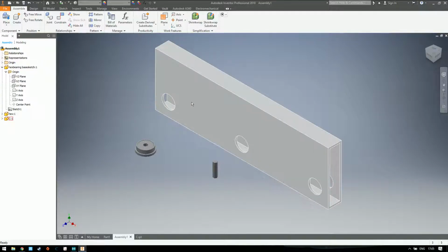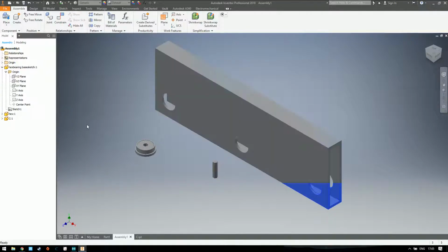But first, you have to choose the biggest object, I should say. Usually I do it with the chassis, one side wall of the chassis. Left click on the arrow, open the origin. Then close everything else. Open the origin of the assembly, usually the third folder under it. Click this left arrow. You can see there are some planes over here. For the piece you identify as center, every plane is constrained to the assembly's planes. Constraint is pretty much just attaching two things together.